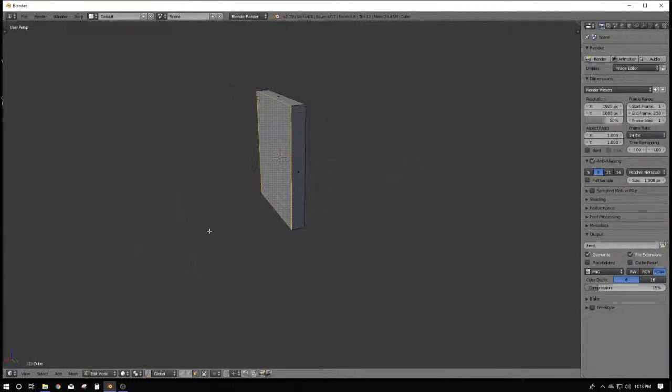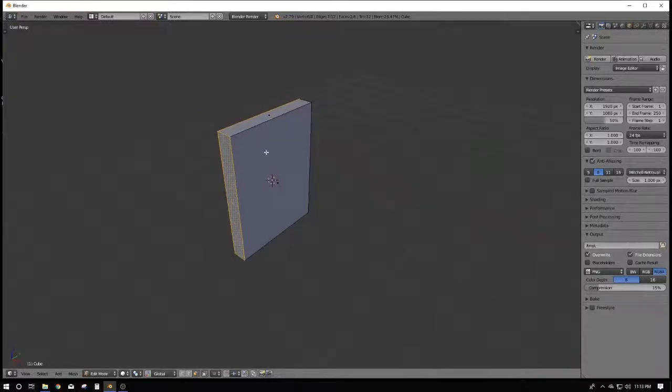So go ahead and come down here and select the Face Select tab. And let's select the front. Hold down Shift and select the back. You can let go of Shift and pan back around and hold down Shift again to select the back side of the cover.